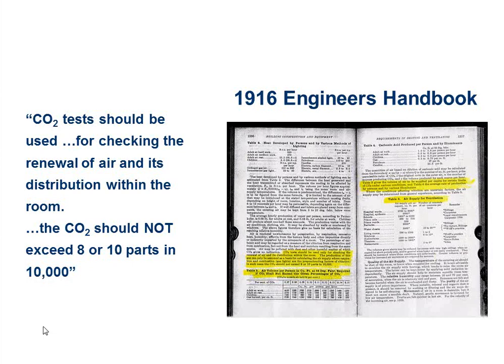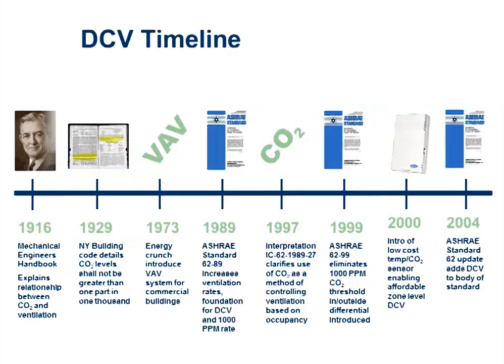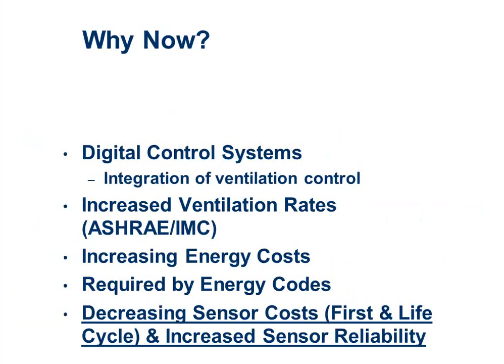Those CO2 numbers, through all those handbooks and codes and ASHRAE, those CO2 numbers are what ended up dictating the ventilation rates in the VR procedure to begin with. So it's not that CO2 is being now permitted by the codes, it's that CO2 actually really formed the codes. You just didn't know that that happened in the background on the calculations when they set up the numbers. So there's the history of CO2. We'll skip over that, but it really got active in the 90s and 2000s and became very code accepting in the 2000s, by name, if you will.